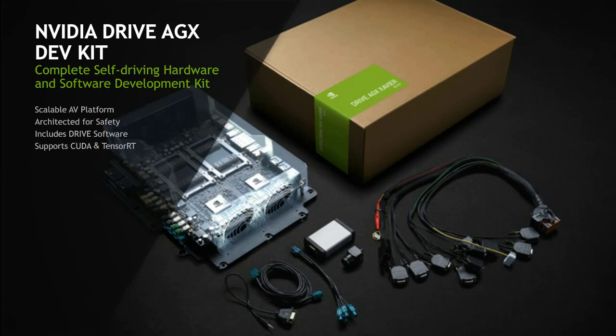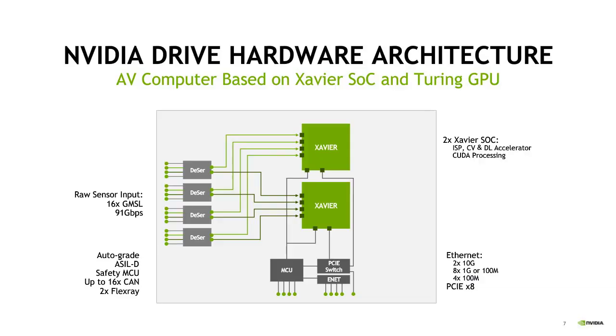The Dev Kit includes a Drive AGX computer, along with a vehicle harness to connect the platform to the car, an international power supply, a camera sensor, as well as other accessories. The Dev Kit also includes Drive software, which is our open end-to-end in-vehicle software solution. Drive software features libraries, toolkits, frameworks, and compilers for vehicle manufacturers and suppliers to develop applications for autonomous driving and user experience. Digging deeper into the Drive AGX hardware, you'll find an architecture that balances performance, safety, and power consumption.